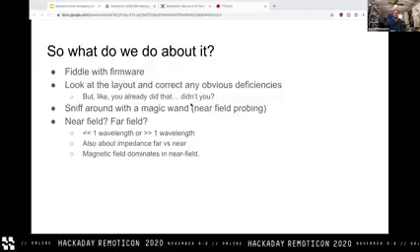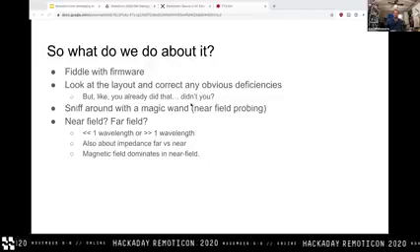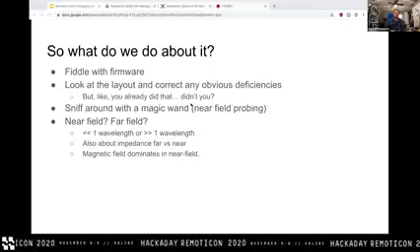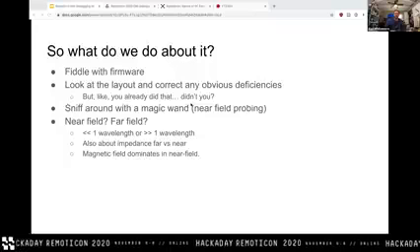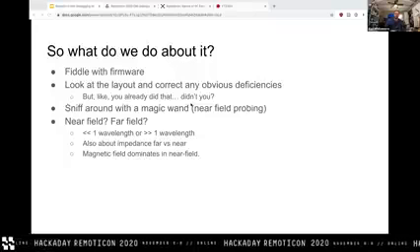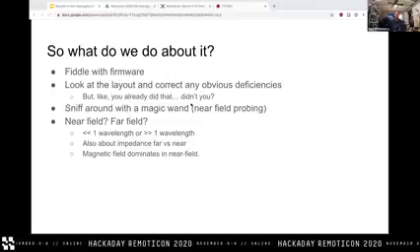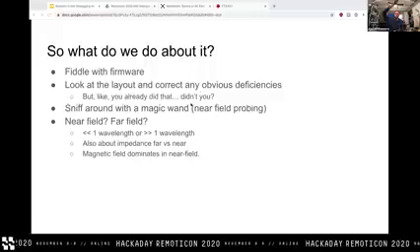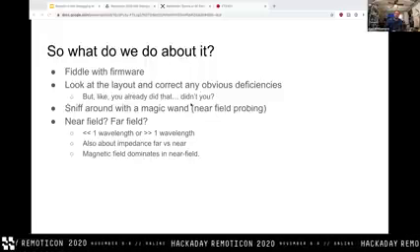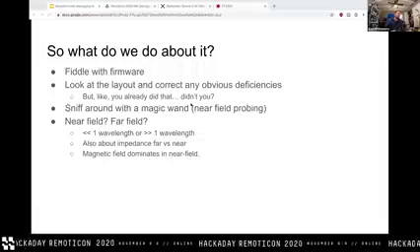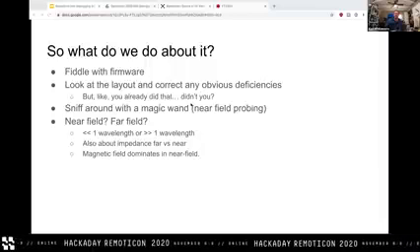And I won't really dive into that because I don't want to dive in deep on customer hardware that I actually have test data for. But you can imagine things that cause signal integrity problems normally, like split ground planes where return current on a high-speed trace has to go around in a big loop around your ground plane split and take a different path to the pin than the data trace itself. All of those sorts of situations can also cause RF emissions. So they can be somewhat easy to spot.